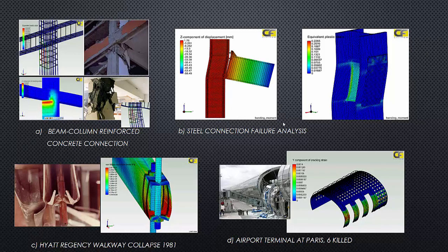Here we have another case. In this case, note the bolts. These are yielded, showing plastic deformation in each load increment. Also, note the extent of plastification in this other picture around the column. Okay. Another case is a real case, the Hyatt Regency Hotel.